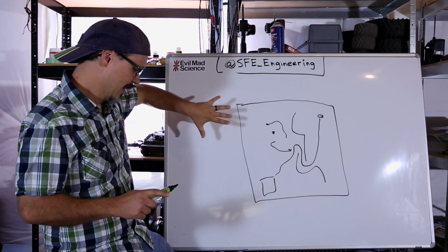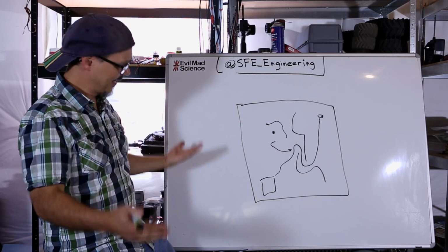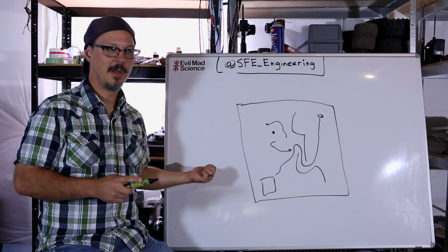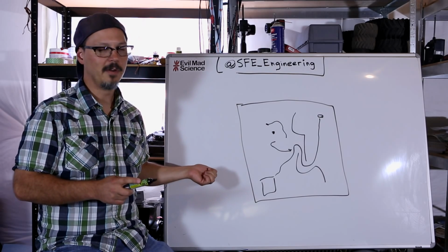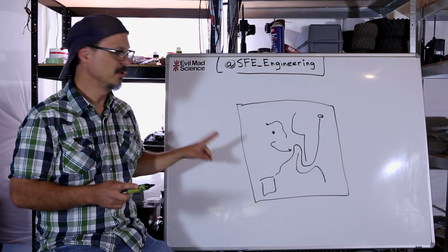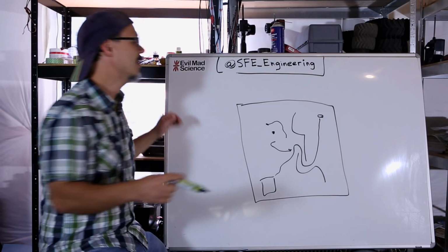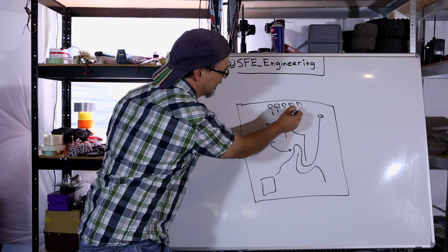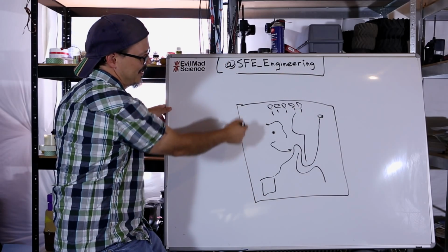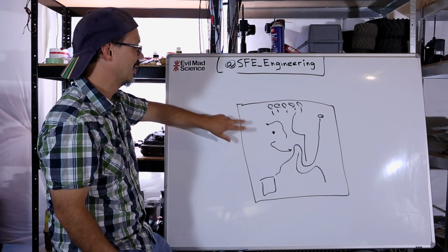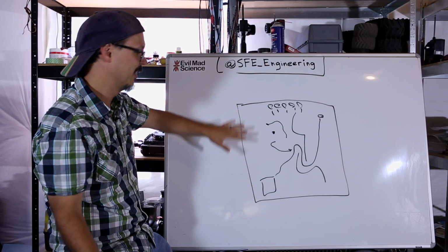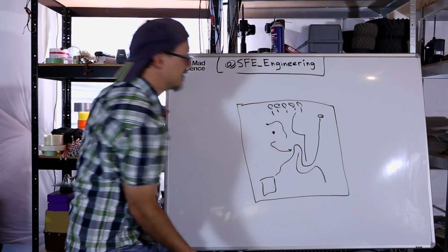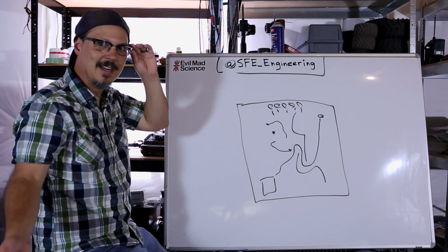Now, after that, we talk about aesthetic things like silk, right? Between the time that you submit this board for prototype and the time that you get it back, you're going to forget everything about this board. So put some silk on it, right? Make it meaningful. If you've got headers up here, label your pins. Things like USB and power in, you're going to know, obviously. But any place where you've got a bunch of different signals, label it, because you're going to need it.